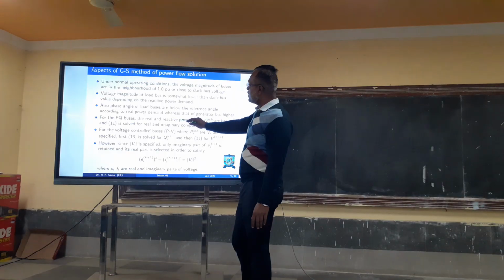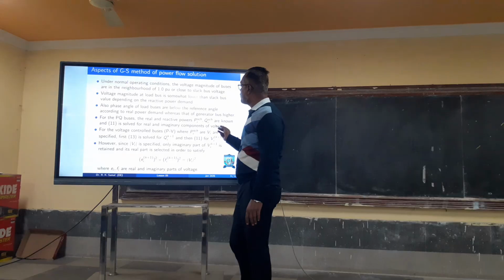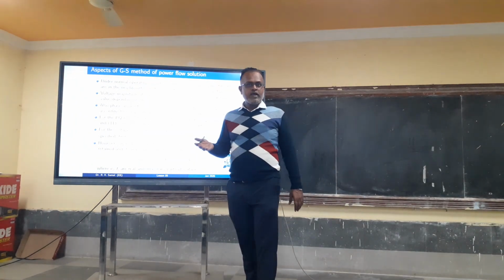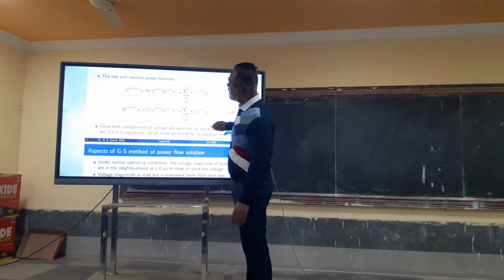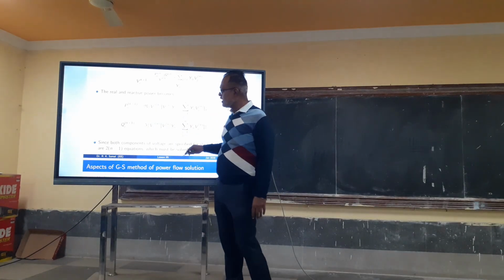For the PQ buses, the real and reactive power are known and the equation is solved for real and imaginary components of the voltage. So for the PQ buses, after getting the voltages, every iteration will solve for Pi and Qi.